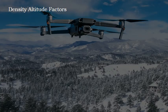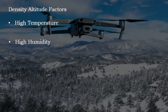So you may wonder what causes high density altitude? Factors include high temperature, where the air molecules become lighter causing them to rise. High humidity. Water vapor found in humid conditions is lighter than air. So the more water in the atmosphere means there is less air, negatively affecting the thrust of sUAS propellers. And low pressure equates to lighter air, once again, making the propellers work harder to gain altitude.